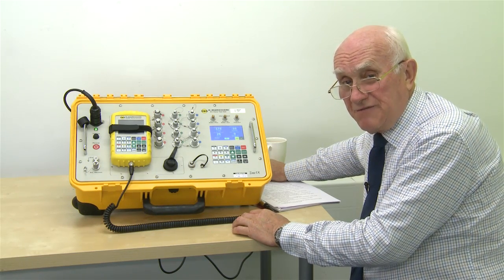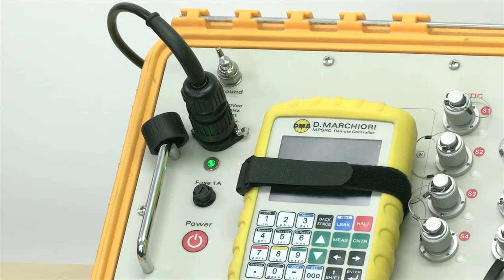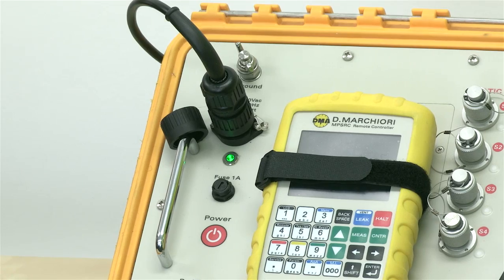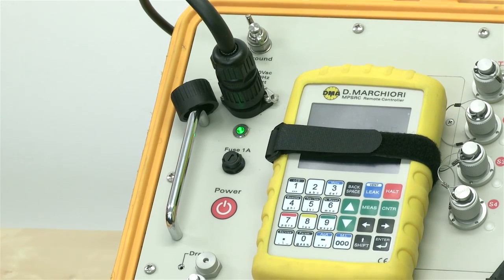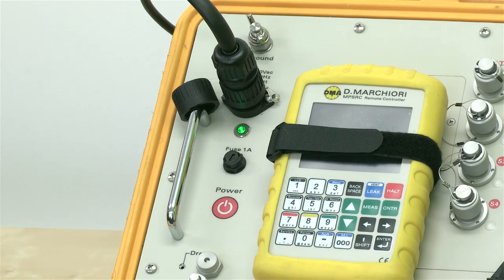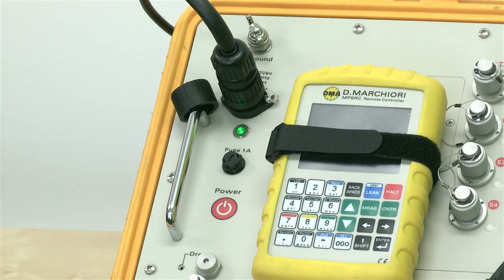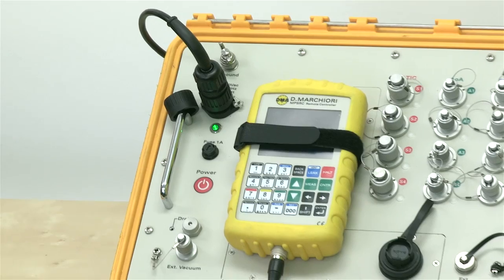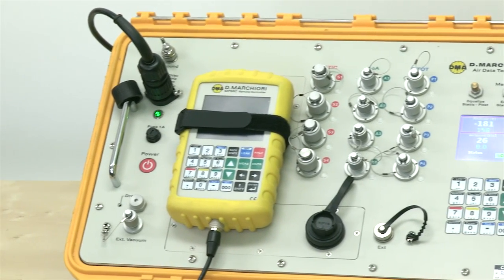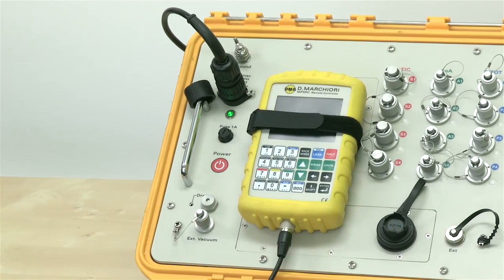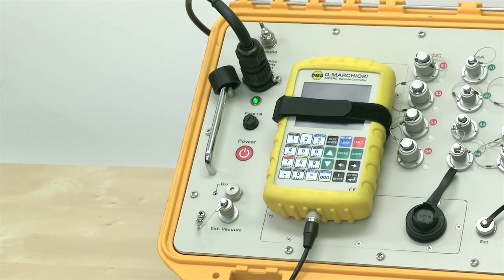We go from 90 volts to 260 volts and something like 40 hertz to 440 hertz. So you're going to be able to run the equipment either on aircraft supplies or indeed on national supplies. You can also, as an option, have in addition a 28 volt capability if you wish, but that's an extra and it's an option. Moving on from there, we have the conventional things like the fuse, the power switch, etc.